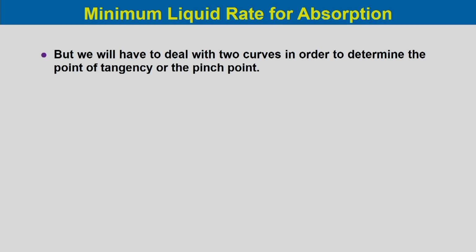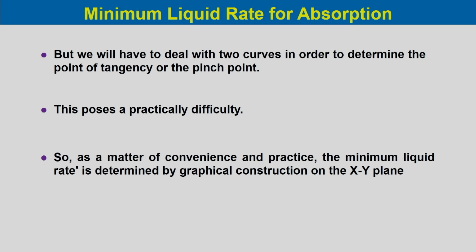However, we will have to deal with two curves in order to determine the point of tangency or the pinch point, because both lines are curved, both the equilibrium line as well as the operating line. So, somehow we have to deal with this, which sometimes makes it difficult to find the pinch point. This poses a practical difficulty. So, as a matter of convenience and practice, the minimum liquid rate is determined by graphical construction on the capital X capital Y plane.